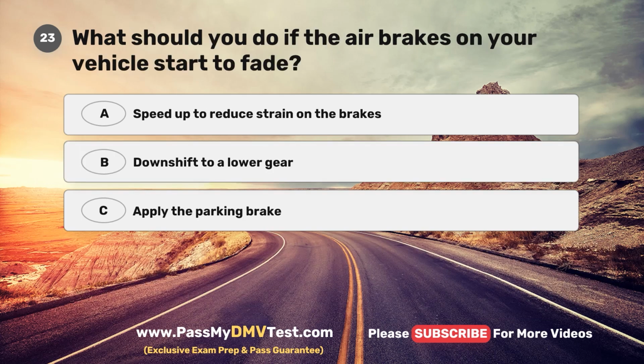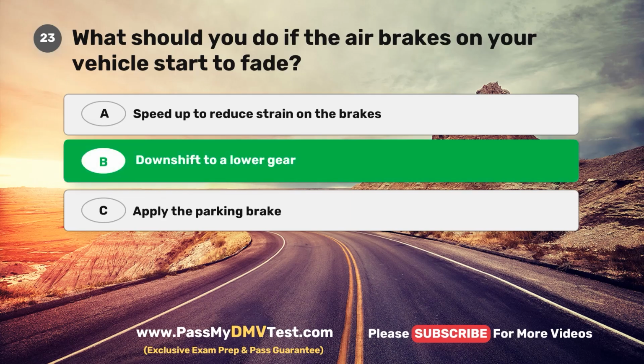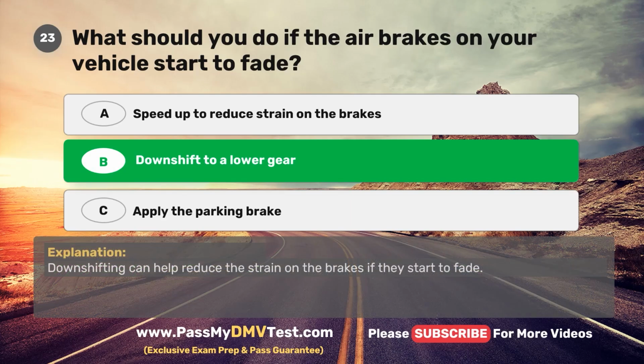Question 23. What should you do if the air brakes on your vehicle start to fade? A. Speed up to reduce strain on the brakes. B. Downshift to a lower gear. C. Apply the parking brake. The correct answer is B. Downshift to a lower gear. Downshifting can help reduce the strain on the brakes if they start to fade.